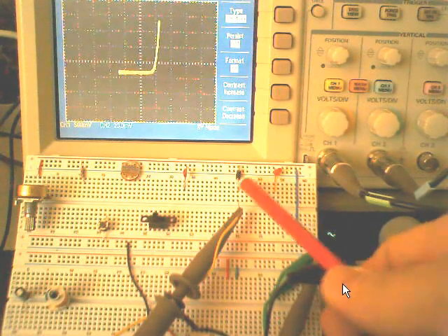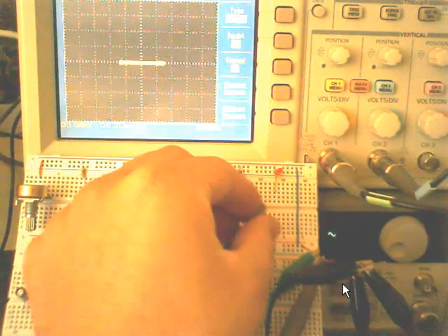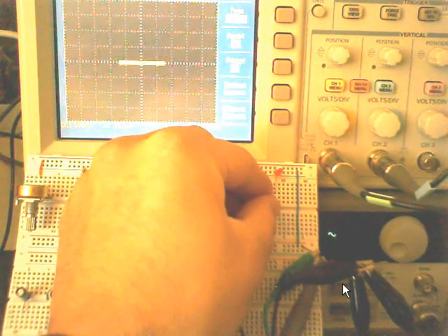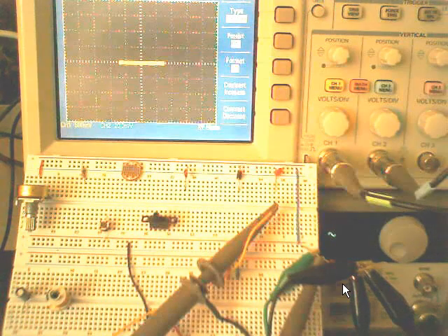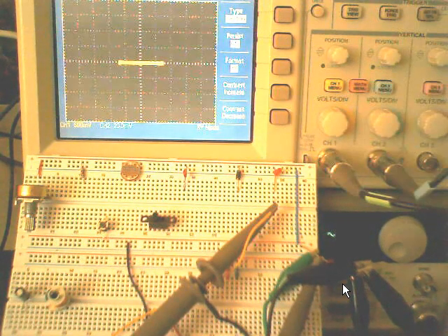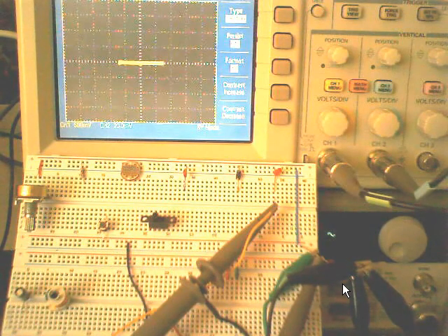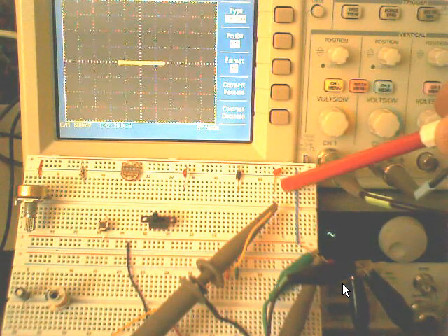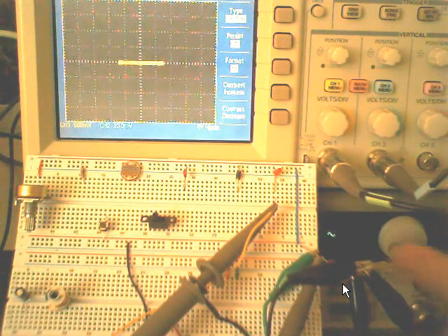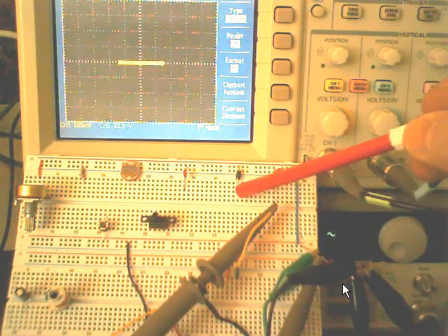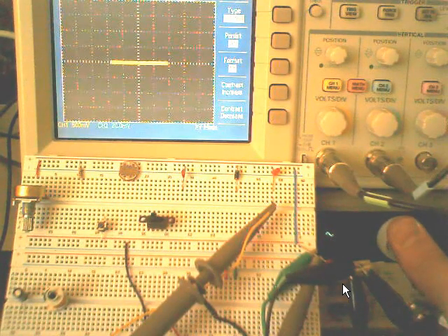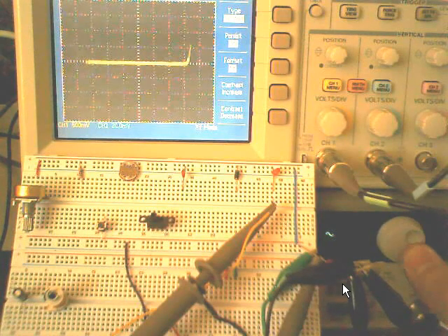And near this diode, there is another component, and it's called an LED. LED means light emitting diode. Its voltage current characteristic is very similar to the normal diode, but it emits light when it has a current. But its threshold voltage is higher than the standard diode. I increase the voltage to show you.